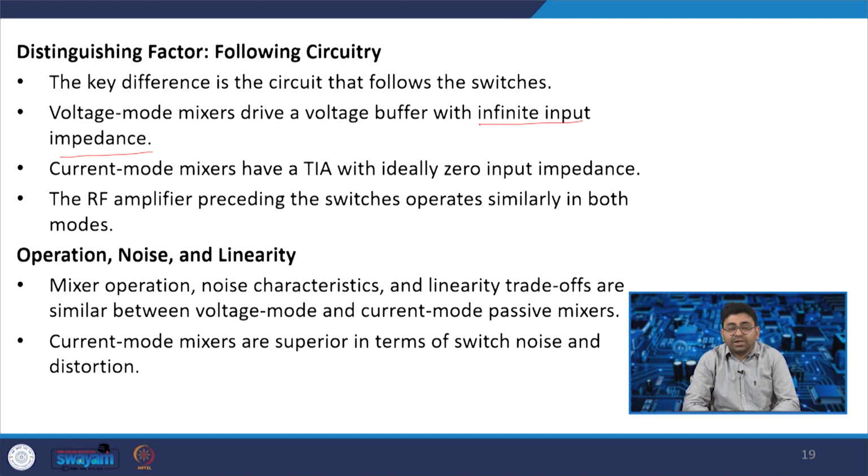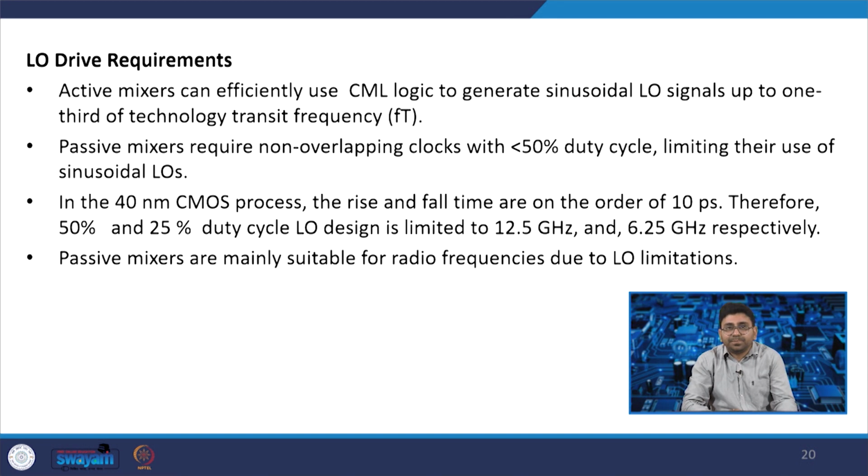Mixer operation, noise characteristics and linearity trade-offs are similar between the voltage mode and current mode passive mixer, and the current mode passive mixer is superior in terms of switch noise and distortion. So current mode is the preferred choice compared to the voltage mode mixer.